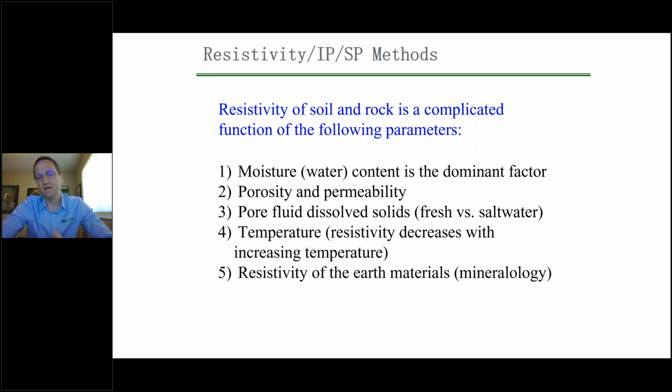And then finally, the resistivity of the earth materials themselves. So you can see that if you're below the water table, if you know where the water table is, determining number 5 is much easier. You can disregard number 4 and number 3 most likely. So this is why resistivity is very good at determining geotechnical or geologic materials, the mineralogy. It's used quite often for that, and also for finding moisture zones for various reasons, or for slope stability when things are compacted along those lines.